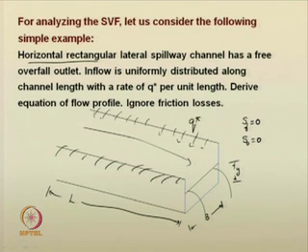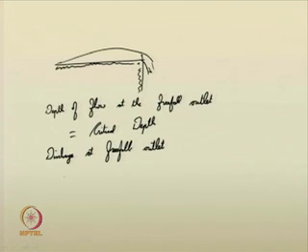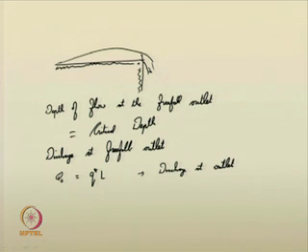So, the rate of increase is q star per unit length. So, we give the quantity Q_0, this is nothing but q star into the length of channel. So, this Q_0 is the discharge at outlet, or you can suggest now that q star is nothing but equal to Q_0 by L.